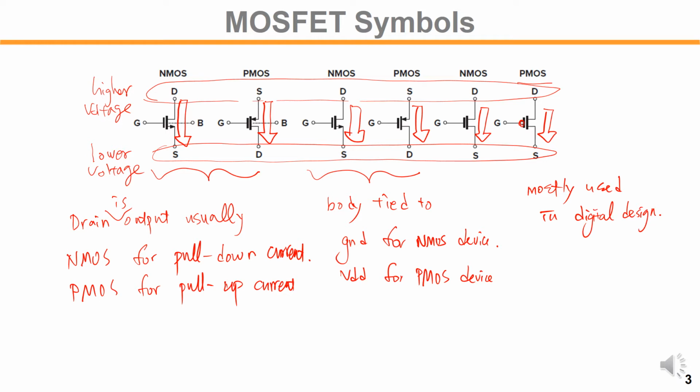And also for small signal analysis like the transconductance, you can analyze that, and so you know the equivalent resistance. So for the NMOS, the resistance looking into the source node, let's say for example REQ. For PMOS also, the impedance looking into the source is REQ here.